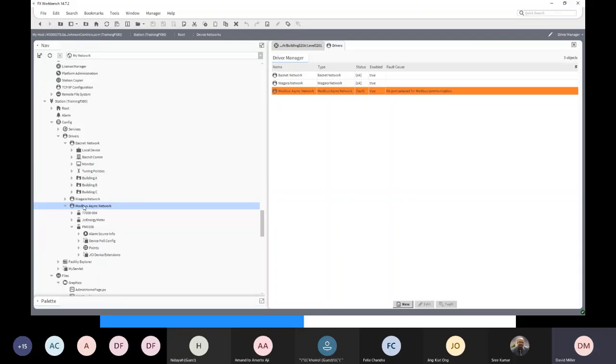It's just the messages that are different. Modbus, N2 and BACnet MSTP are all RS485 protocols, but you can only have one protocol defined on a trunk. You can't mix Modbus and N2 on the same cable.